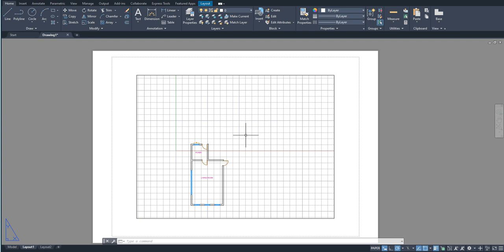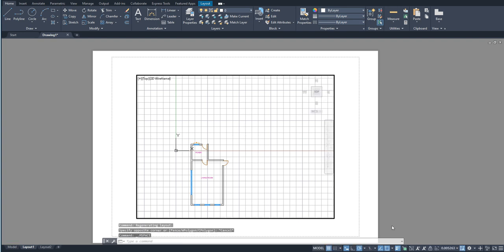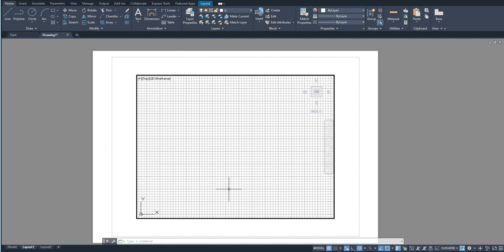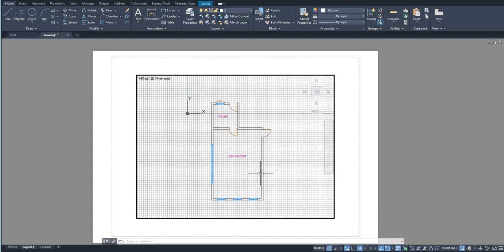So for that, I'm just going to double click inside this. This is called a viewport. These are the different scales on which the viewport is working presently. The scale that is presently here is 0.05263. If I zoom in, the scale over here changes. So if you want to print to a scale, you're going to have to change the scale from here. Over here, I'm just going to click this down arrow and select a scale of 1:100.